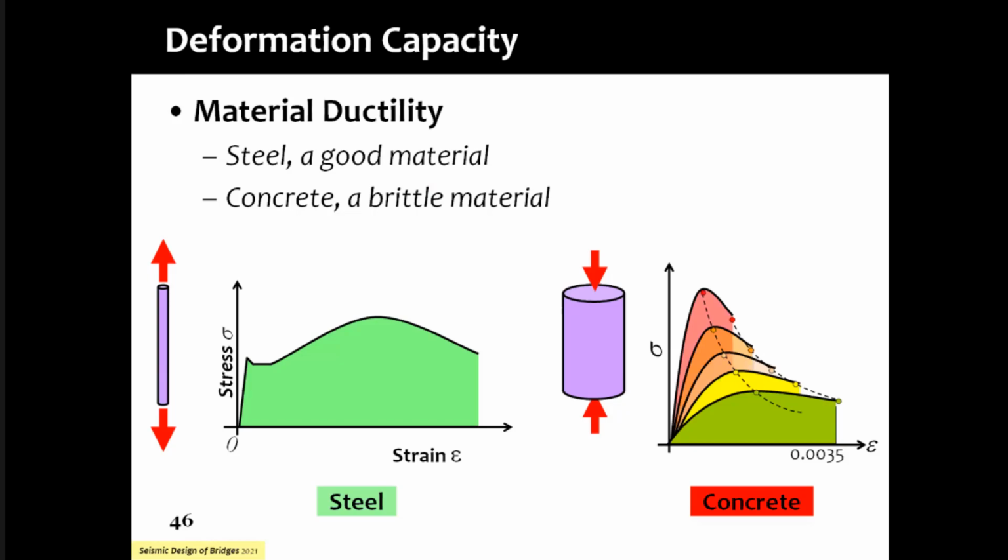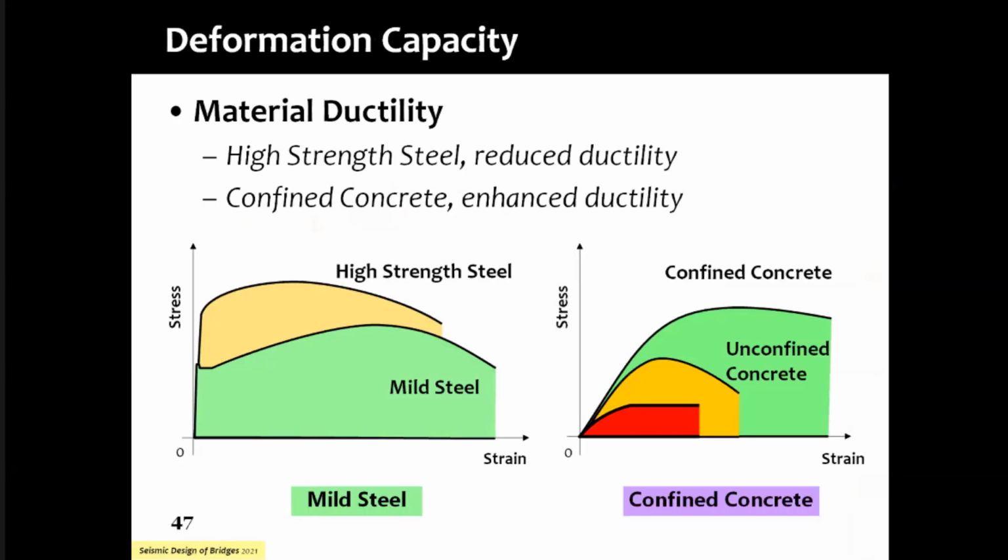The pier is going to be swung back and forth, and we have to make sure that it has sufficient deformation capacity. One of the key factors of increasing ductility is actually confinement. The unconfined concrete has a ductility of 3. In fact, ductility of 3 only for grade M20, M25, M30. If you're going to M100, the ductility is 1. Right? The new IS 456 will tell you that there is no ductility in M100, and above 60 there is very little ductility, 1.2, 1.3, that kind of numbers. So higher grade concretes are not your friends if you're doing seismic design of bridges. Lower grades are your friends.